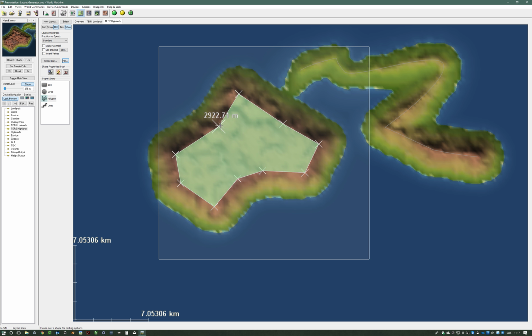There is also a way you can right click and hold the mouse button down, and then you get this quick way of setting the elevation of that point. And now I'm doing it on a polygon like this, and I've never got any effect from it. So setting the individual value for one of the vertices seems to only work for lines and not for any of the other shapes.